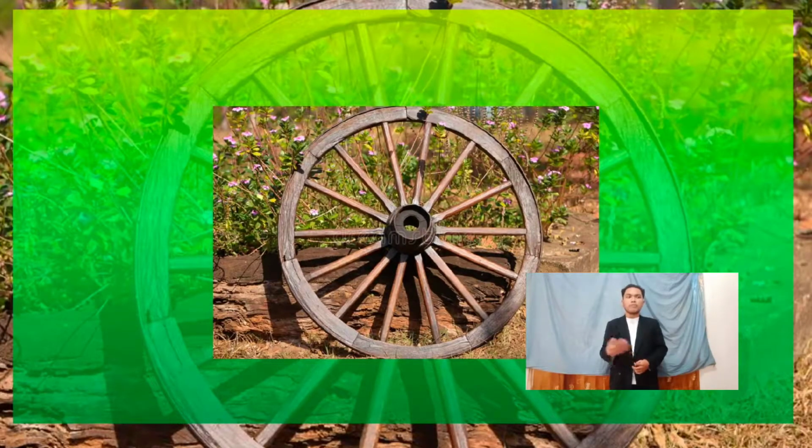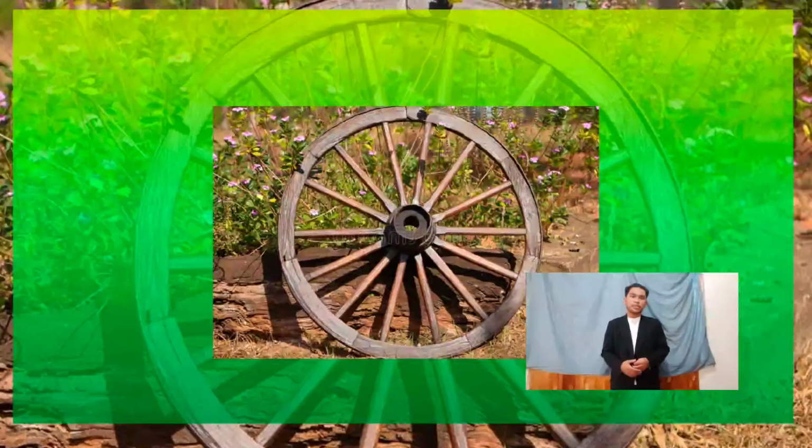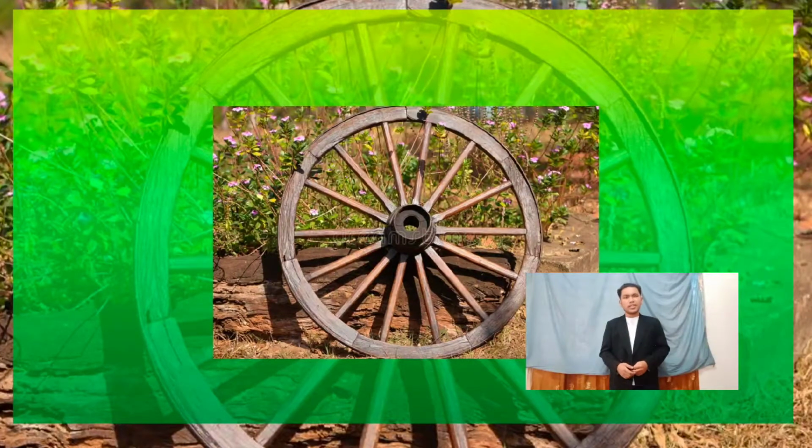Now, after that, they cool it down so that it compresses back to its original size. But with it already on the wooden wheel, it compresses on the wooden wheel, making it a firm fit so that it will not separate from it. Now, isn't that ingenious? They saved iron from making a bigger iron rim, and also they used thermal stress in such a fascinating way. Now, to learn more about thermal stress, up next is the derivation of equations.